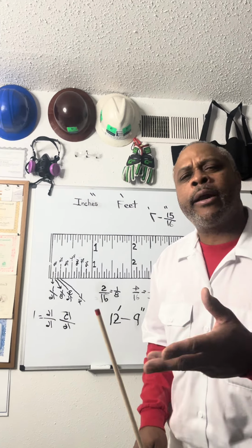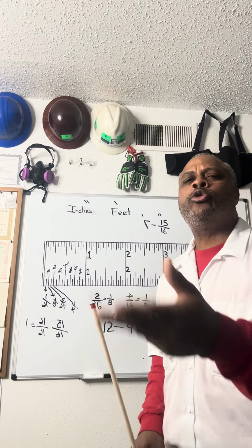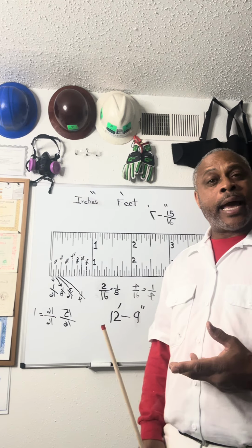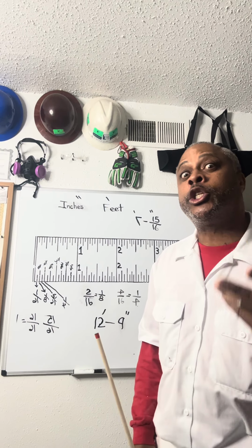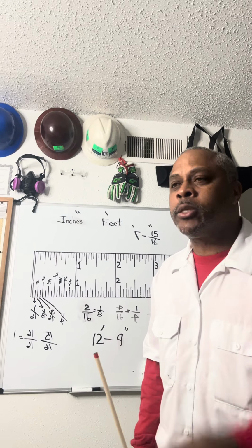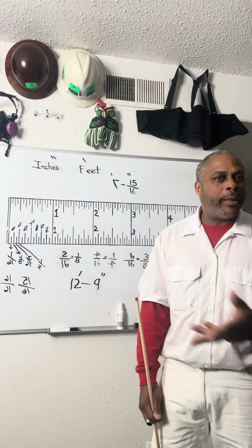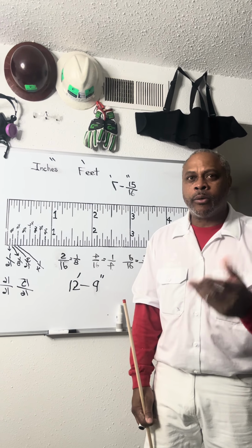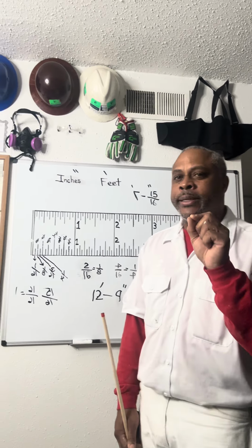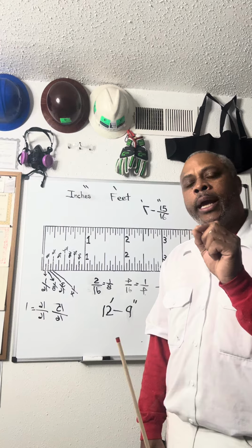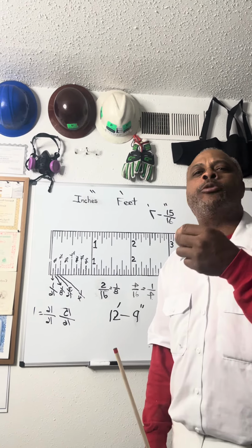Well, because they did not read in the beginning how many nails it told you to put or what size nail. I see guys buy nails on a construction job requiring commons, and they're buying sinkers, and they put them in the gun, and sometimes it's hard to tell, and then they overshoot the nail into the plywood, and it sinks in and goes past.